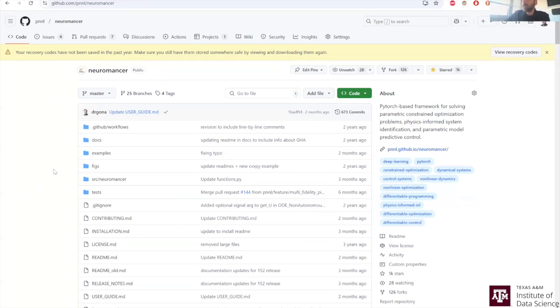If you have a partially observable system, but all your controlled variables are in your observable space, it's not a big enough issue. You will come up with some kind of surrogate model that will map your observables to the next state, and because you are controlling only observable states, you assume that the model, the input-output system that you are choosing, is implicitly capturing those unobserved states.